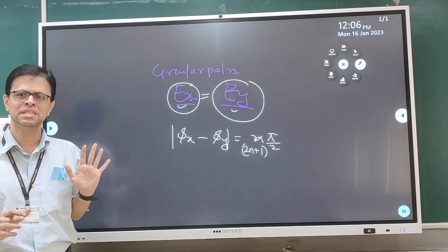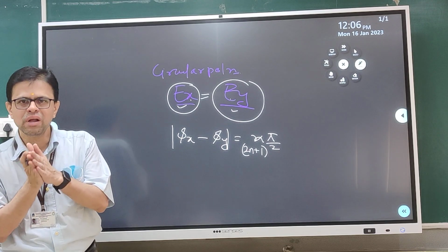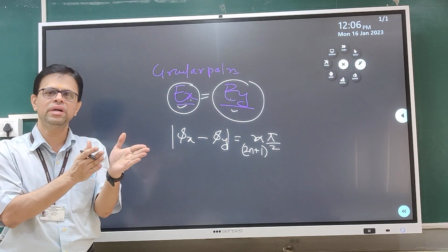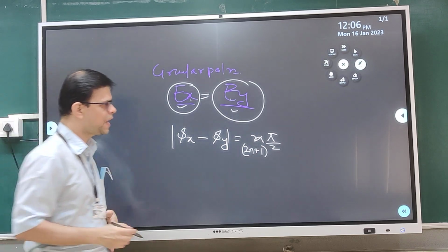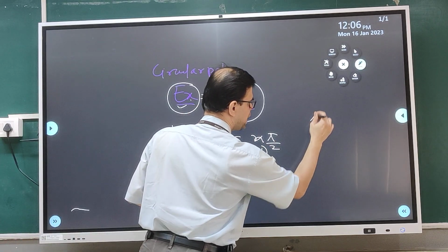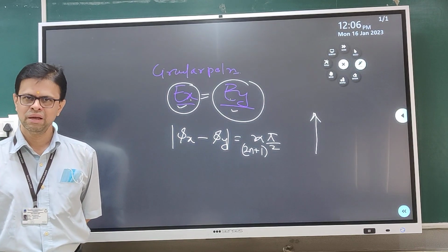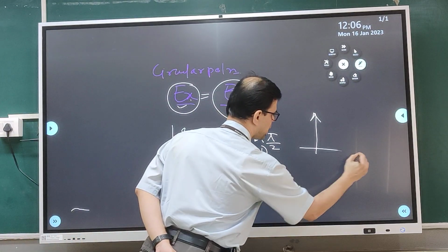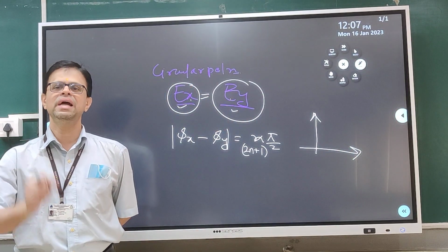Now based on this, I will try to correlate how the cross polar level is important in the radiation pattern measurement for CP design. Now remember, as I said, if my transmitter polarization is vertical and my antenna polarization is horizontal, as I mentioned earlier, you will get a signal loss.